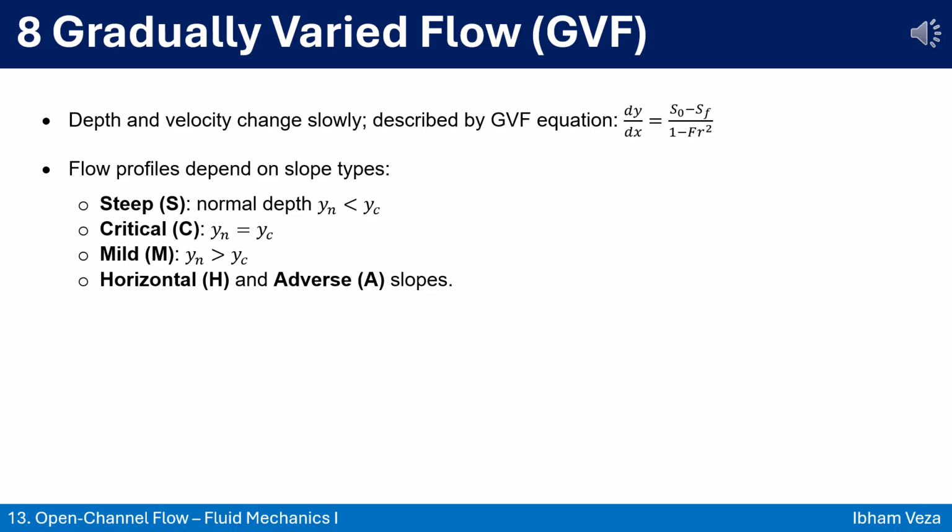If you know the slope and the type of flow, you can predict how the water surface will respond. GVF helps you anticipate backwater curves, drawdown effects, and control structure performance. It's not just math, it's a map of how water adapts to terrain.